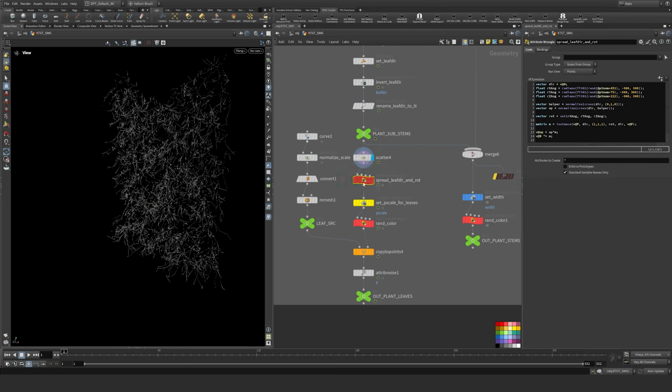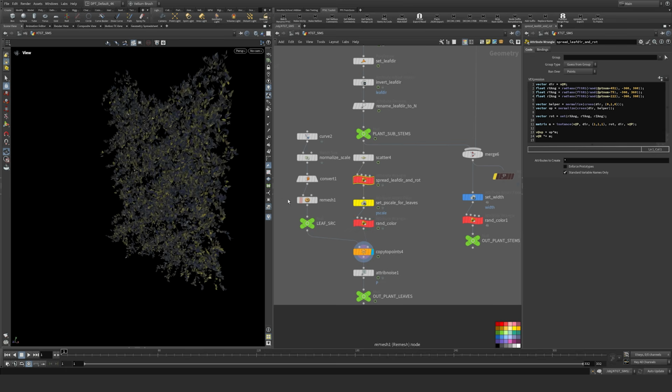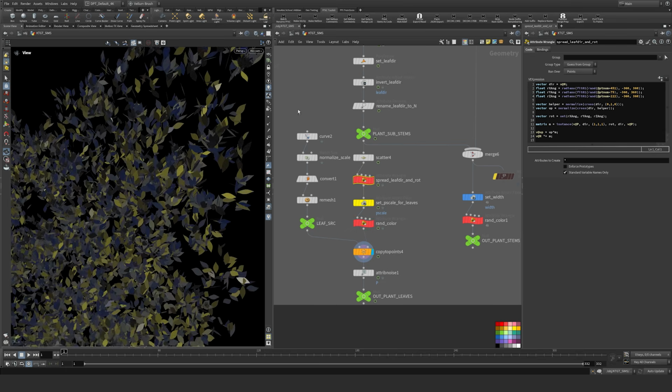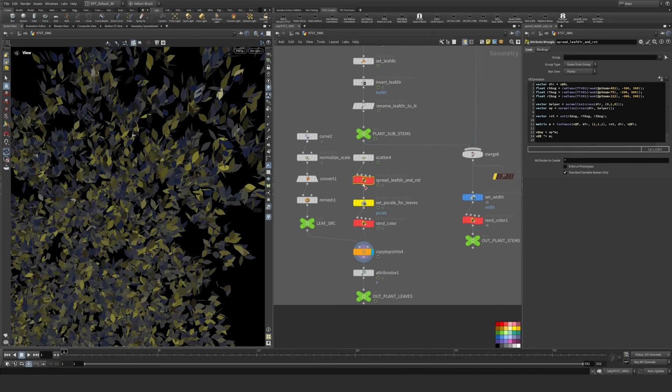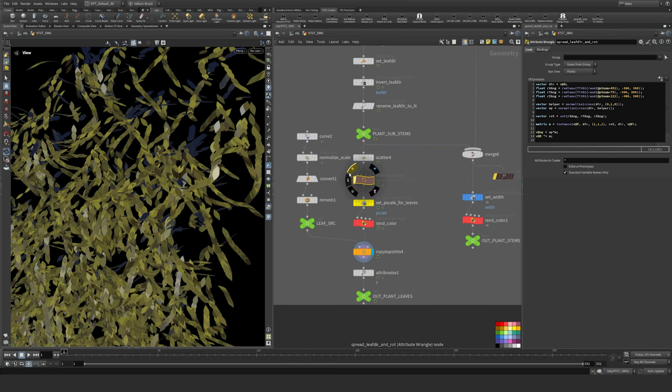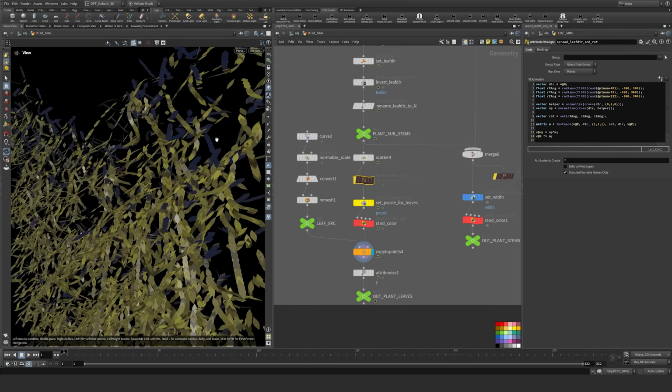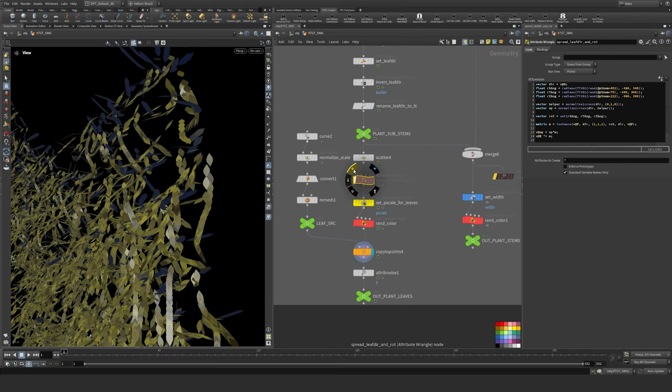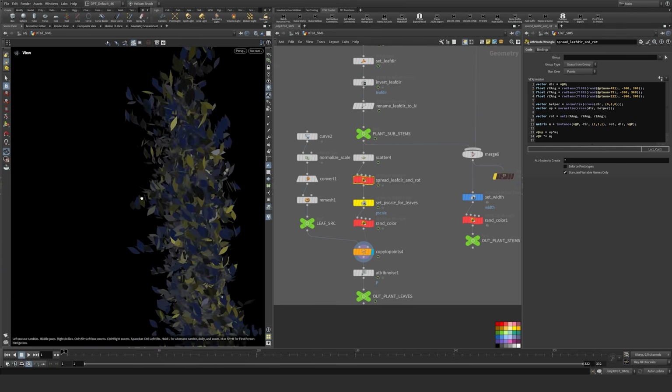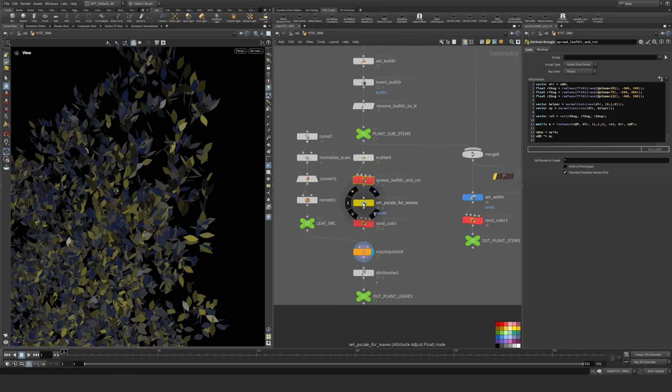Same for a lot of the transformations for which way these are oriented. I did a custom setup here so I could set my up and N attributes. That way, once we get down to the copy, the leaves are twisted in the directions based off of that. Without this, they all copy on those curves. So this has helped spreading things out as well as twisting them so they're in randomized directions. The p-scale obviously changes the scaling, and the color is the color.